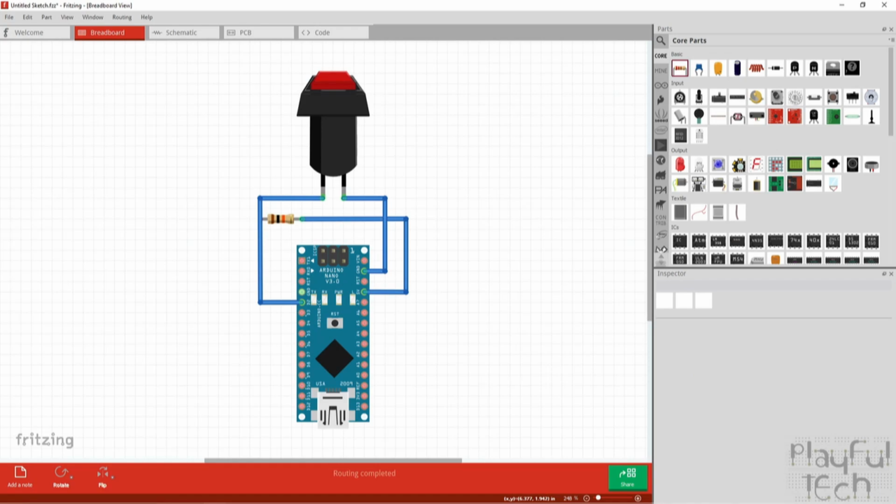Although it might seem counterintuitive at first to have the default state as high, that's actually preferable. It's more resistant to noise, and it means you can use open collector devices. These are devices that don't ever drive a signal high. All they do is pull it down from its default state to ground. And that's how the I2C interface works, for example.